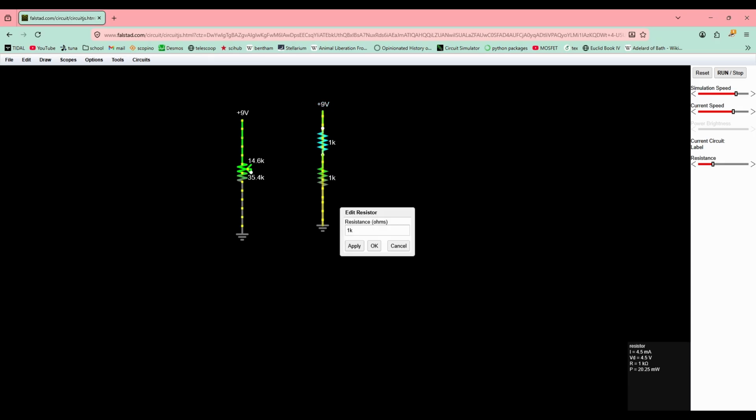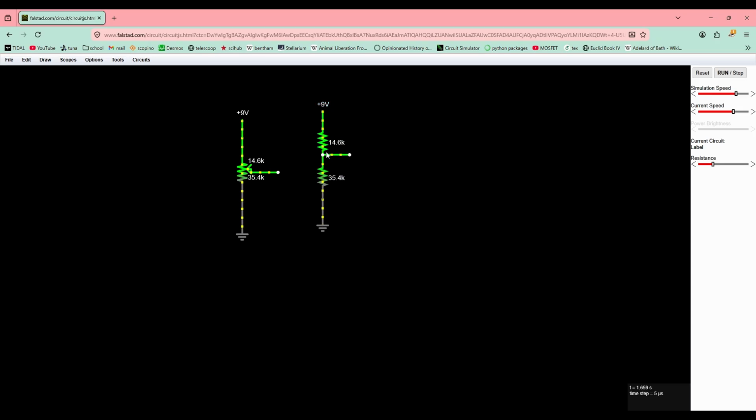So now you see a current flowing through here. This circuit is equivalent to the circuit that you would get if you replace this variable resistor with two resistors that are the exact same value as the resistor over there. So these two circuits are equivalent, just to illustrate how the potentiometer works. Only this left one I can move around easily, and this one is static.